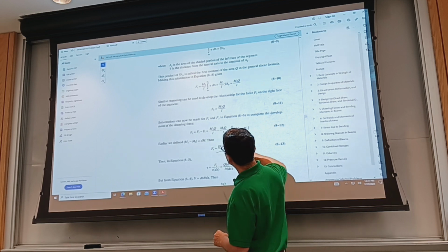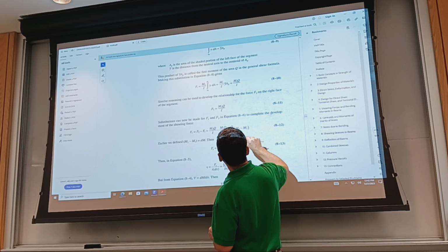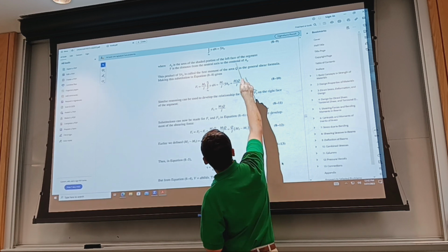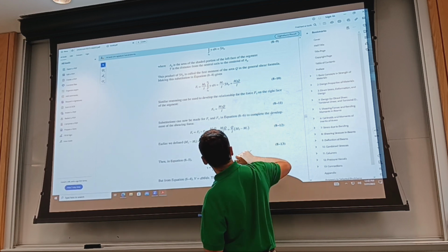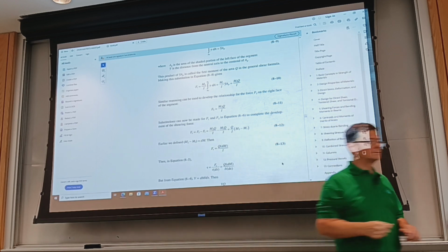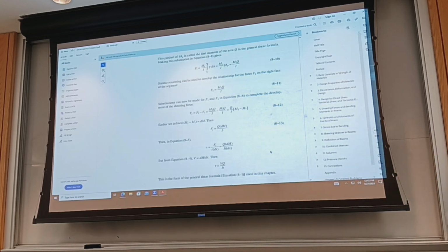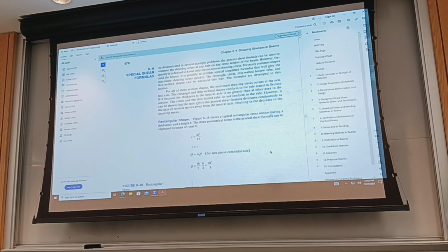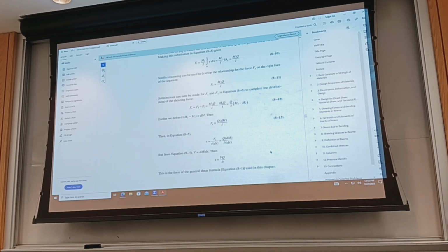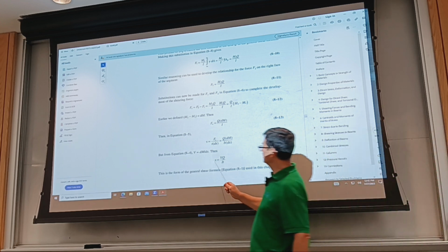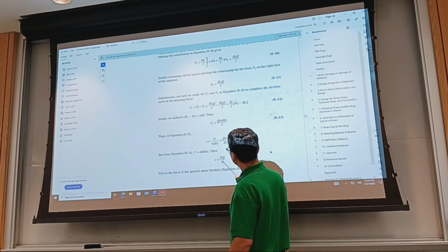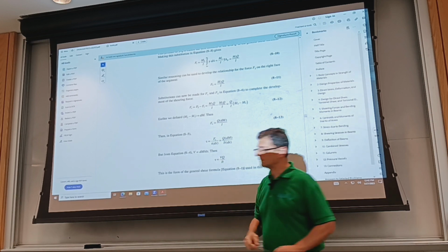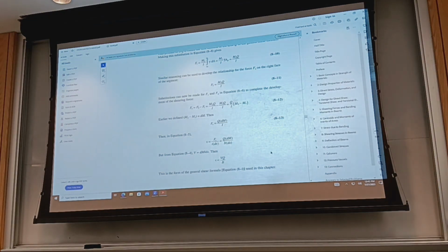And we've got this difference, introducing the areas and distance to the centroid. You saw it earlier. So the next step would be to confirm the equation that was introduced earlier. So that's a repeat of the equation before, it does not have a number. So shear stress at that location, from the diagram, is first moment of area over moment of inertia times thickness.